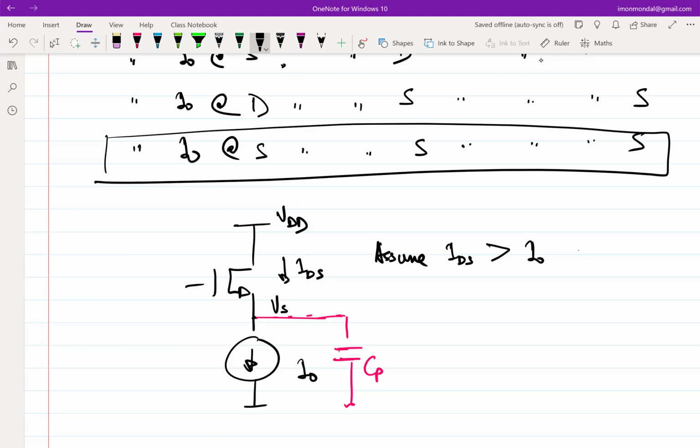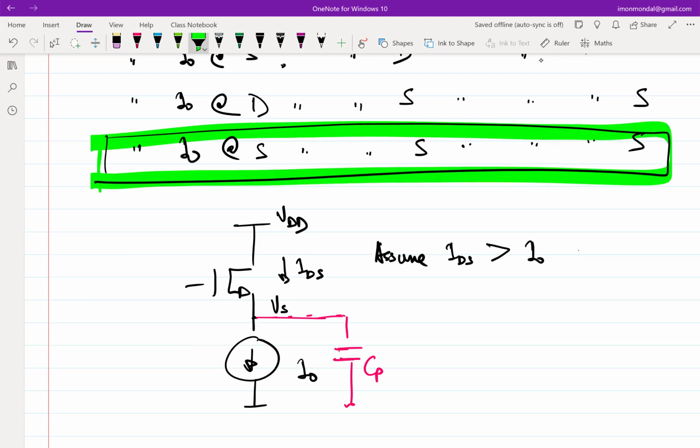Affecting the gate voltage is one of the possible scenarios, but note that I am now saying that I am not going to touch the gate, because we want to take the corrective action at the source itself, not the gate. Yeah, increase the source voltage. Let me take a step back. If I say that I don't want to touch the gate voltage, I cannot keep it hanging, right? I have to connect it to some fixed voltage, whatever it might be. Just like we connected drain to VDD, let's say I connect it to some fixed voltage VGQ.